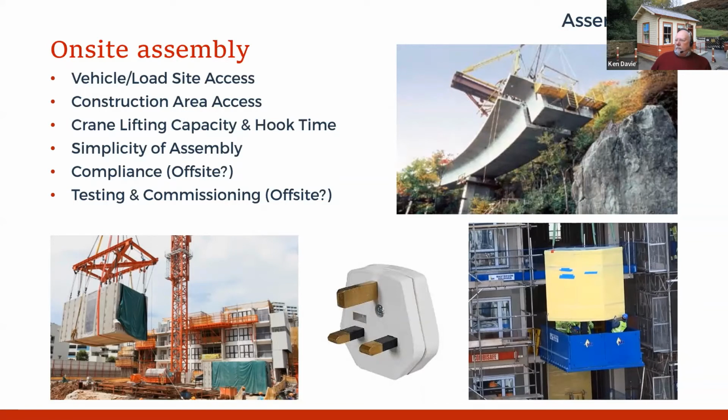One of the techniques for off-site manufacturing assembly is foolproof assembly. If you think about it, the 13 amp UK plug is designed to go in a socket, and in theory you should never be able to put that plug into the power socket the wrong way. The Japanese have a term for that, poka-yoke, which is about foolproof assembly. It's a technique that can be used for off-site manufacture, where the different assemblies are designed such that they plug together. They can only go together in one particular way.